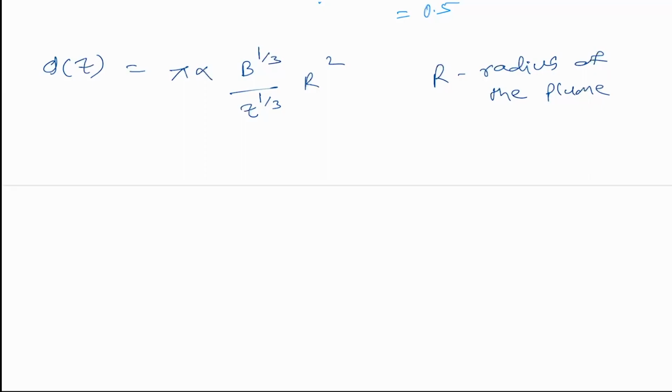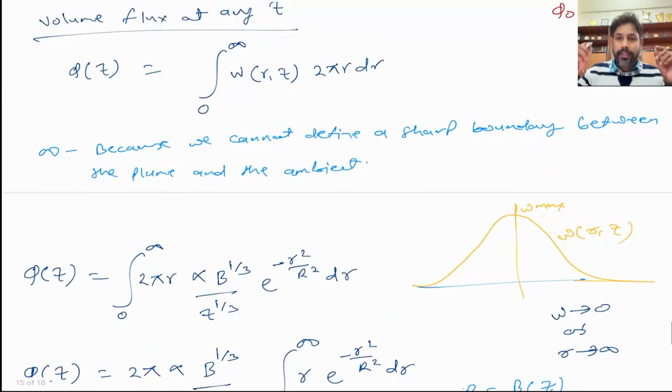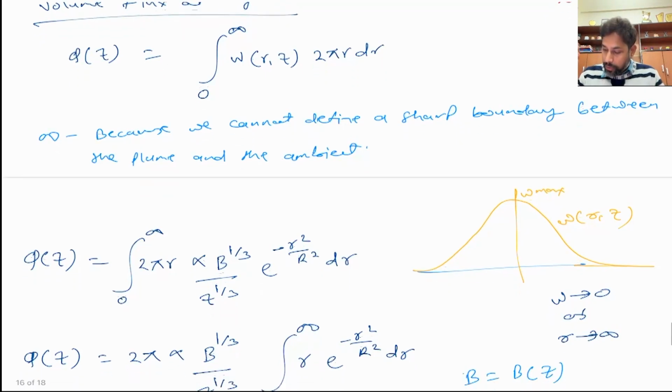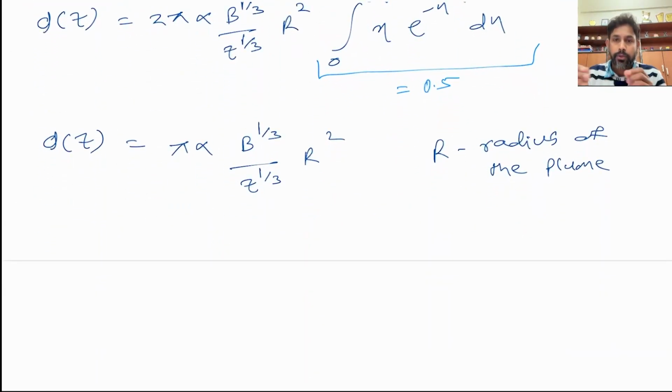So now this is something that is a little controversial or self-contradictory, because we just said that plume velocity does not become zero except at infinity, and then we are defining plume radius, and by plume radius we would mean that beyond plume radius the velocity is zero, right? So here we assume that this parameter is particularly found using lab experiments, and there is some threshold defined beyond which the velocity is assumed to be zero, and within which there is velocity or there is plume.